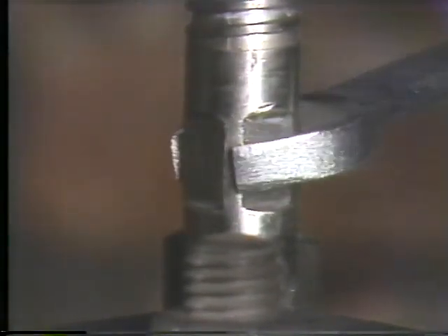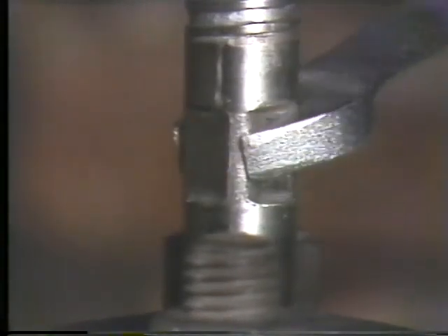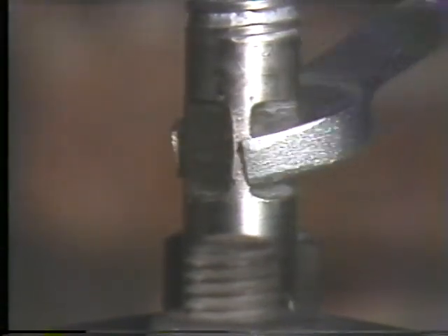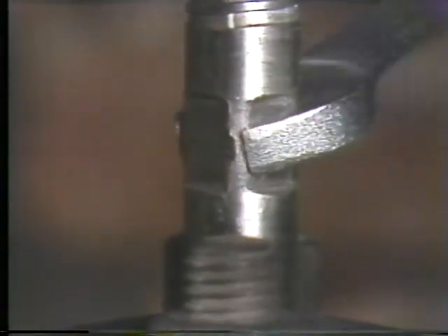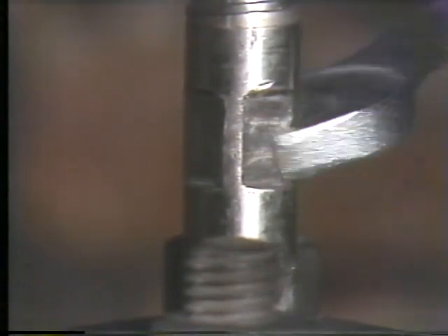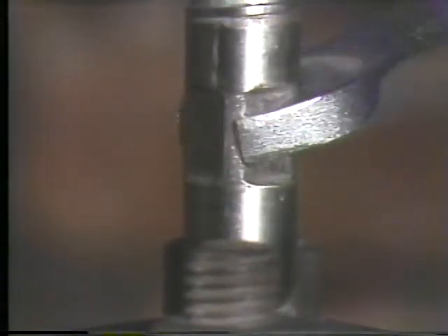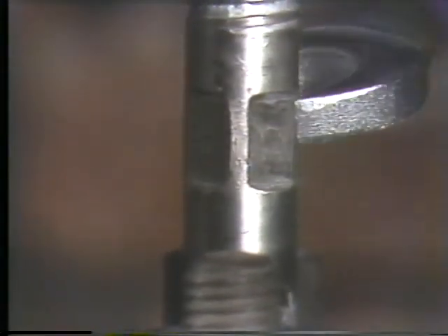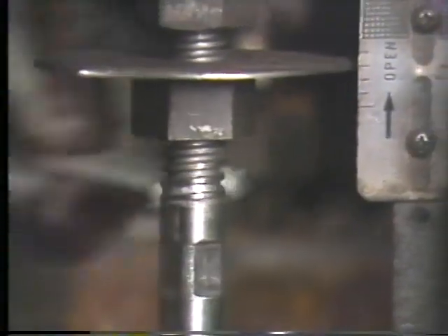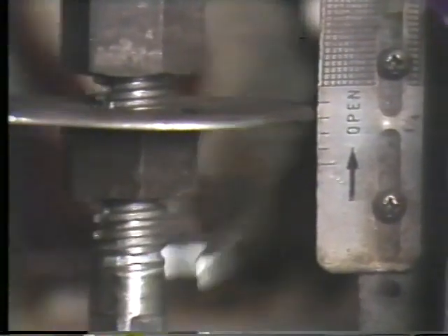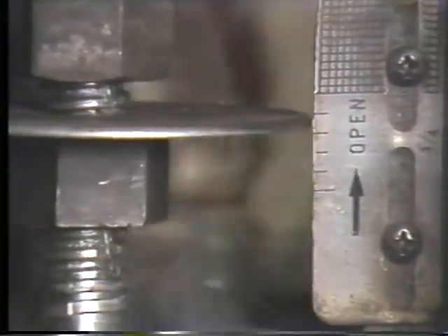Then, again, without touching the small hex nut, turn the valve stem with a wrench. Be sure to apply the wrench only to the flat part of the valve stem so you don't damage the threaded part of the stem. What we're doing by turning the valve stem is screwing the valve stem up into the long hex nut that is connecting the actuator stem with the valve stem. In doing this, we are opening the valve.